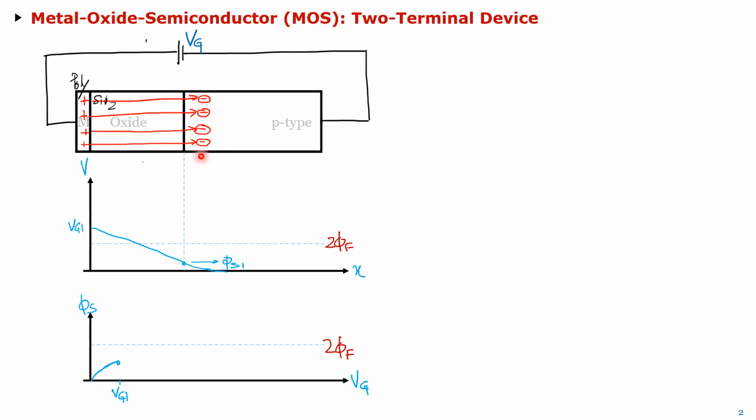In the PN junction depletion, you see how the potential drops like a parabola, right? The key to changing this type of material is if the potential on this surface here becomes equal to 2 phi f. And I explained last time why 2 phi f: because the Fermi potential is phi f below the intrinsic Fermi potential. So if I want to invert it, I want to go 1 phi f above, right? So if this potential goes above this line, this will change to an n-type.